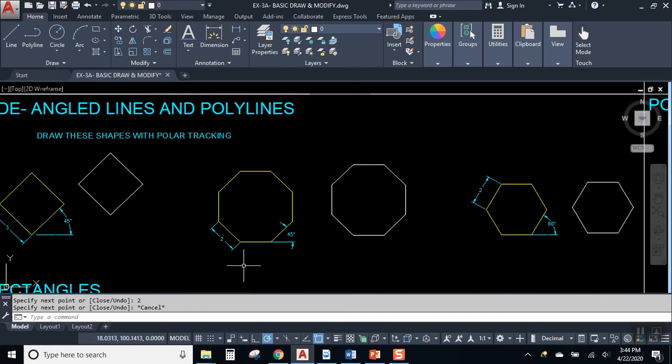It not only lets you go at angles, it also lets you draw wacky angles if you want to go off the grid, right? So look, I can get perfect angles, or if I'm just kind of playing around and drawing stuff by eye, I can make whatever angle I want. Ortho locks you in. You could never draw that line with ortho. So my suggestion is, why draw with the ortho when you can use polar?